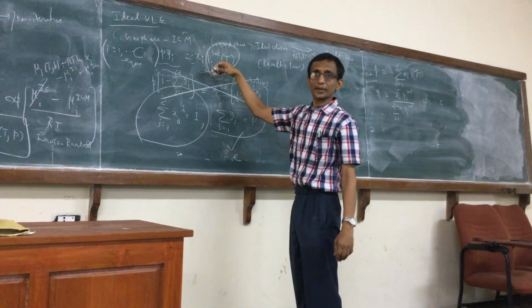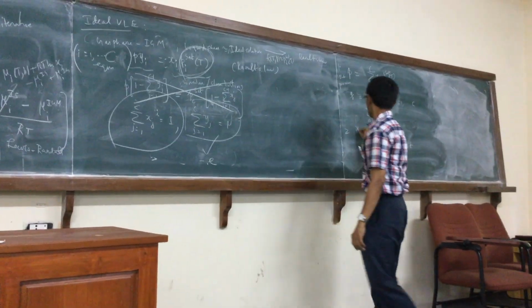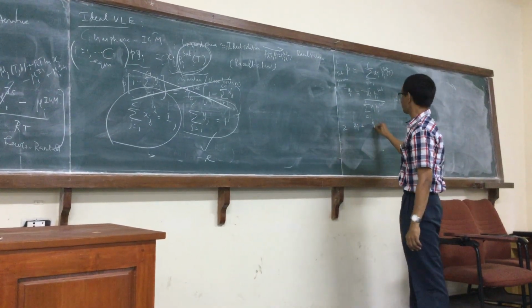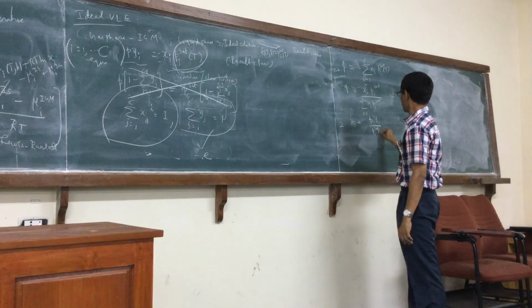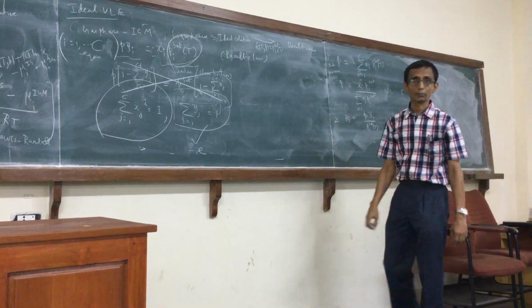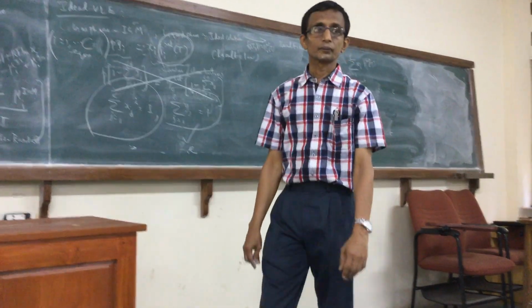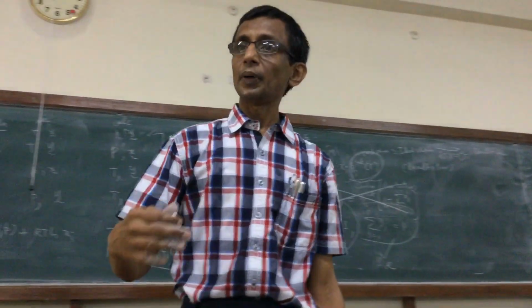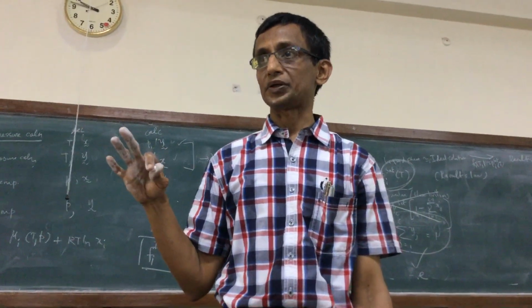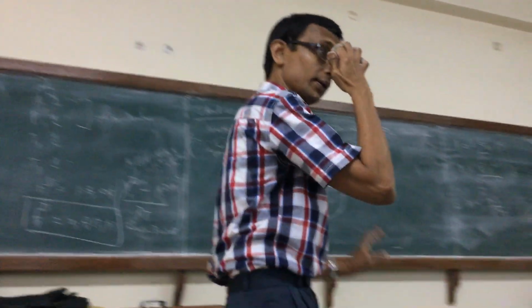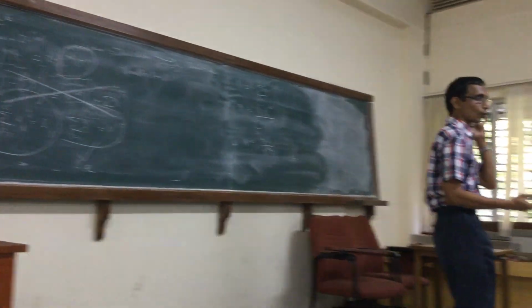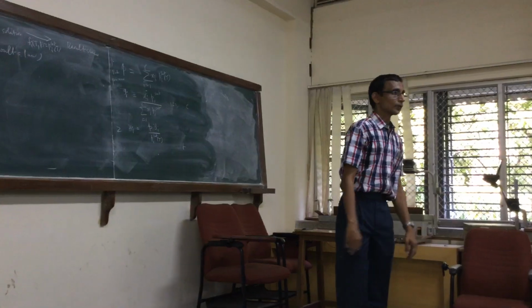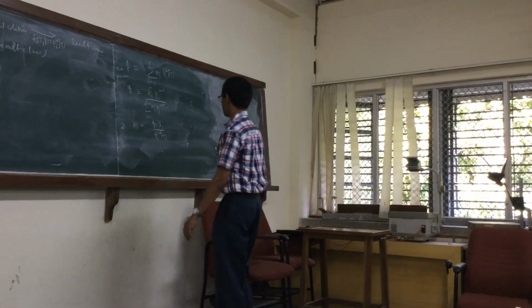So what I do is, I don't add up the equations directly, but what I do is I write this as xi is equal to P yi by Pi sat of T. Okay, I always want you to keep remembering that Pi sat is a function of temperature. Because here, that is where the explicit temperature dependence comes. When you go to non-ideal cases, that is one of the quantities which will have temperature dependence. So you cannot just treat it as a constant.